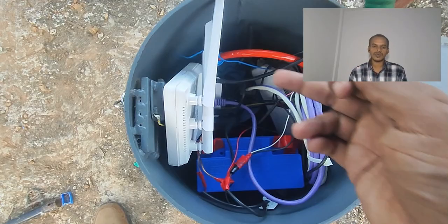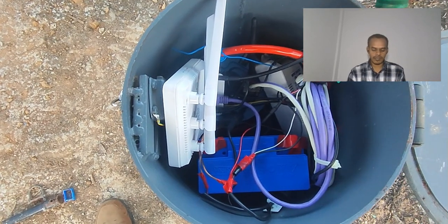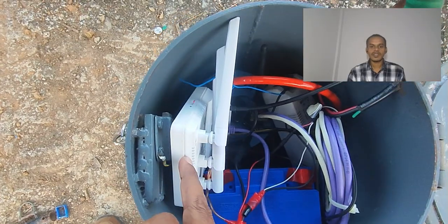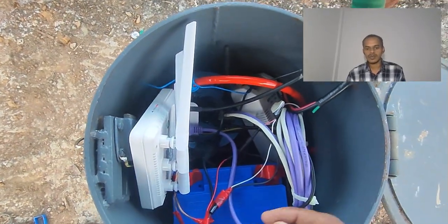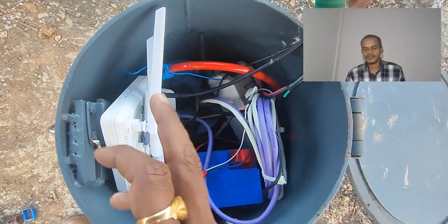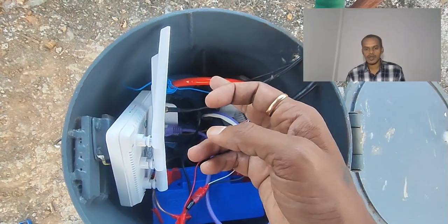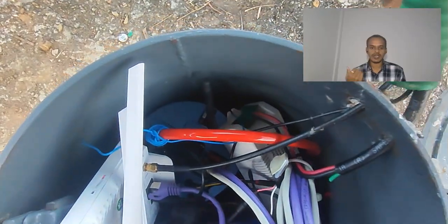You can also go for different kinds of telemetry systems like VSAT, that is very small aperture terminal, or you can use satellite communication, or you can directly use the LAN system for data transmission. This router is giving you the data, and without this the data will only be stored in the instrument and it cannot be retrieved to the system.